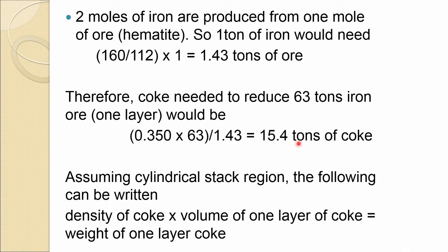So, 15.4 tons of coke is needed. Now, you know the amount for the coke also. You can assume the cylindrical stack region, then you can easily find out the thickness of the layer by a normal volume, knowing the volume of the one layer of the coke.